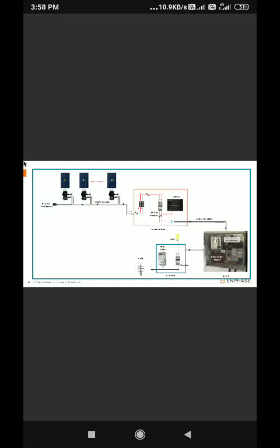So in this drawing, if you see, each panel has a microinverter connected to the frame of the panel or to the structure just beside, behind the panel. Okay, and the DC is connected. The DC polarity is connected to the DC terminals. You can see the top MC4 male and female connectors, which come from the panel positive and negative connectors. Okay, and then the Q cable, we have a Q cable, and this is Enphase patented cable.